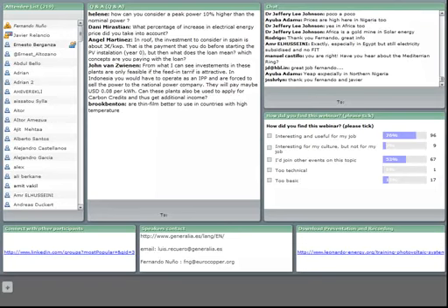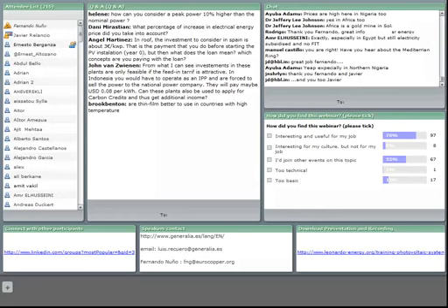And well, the answer is that the thin film module technology has a better performance with temperature than crystalline modules. So the answer will probably be yes, if we can get cheap thin film modules in that country, because we can consider 4% system losses if we are using crystalline modules for every 10 degrees over 25 degrees.